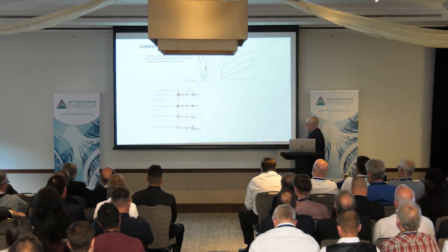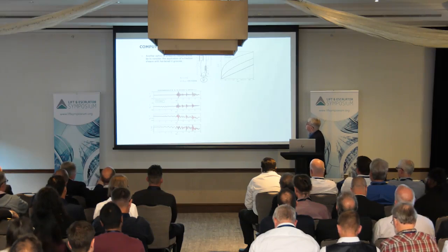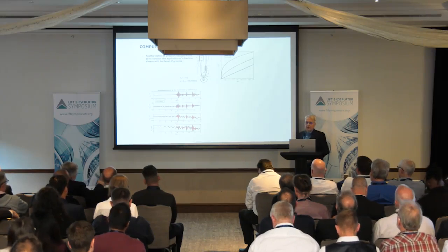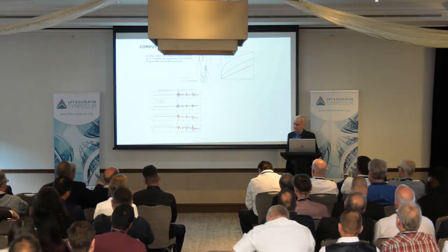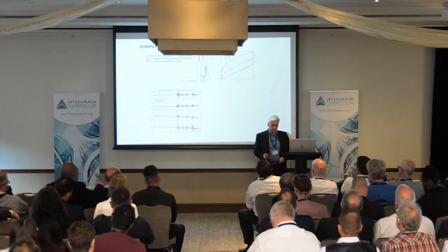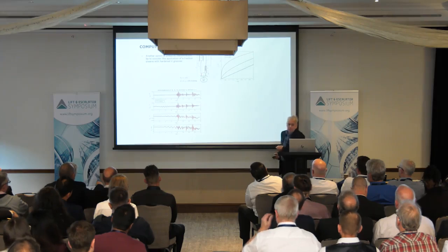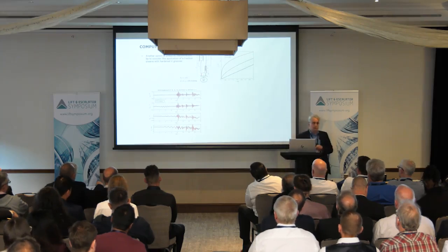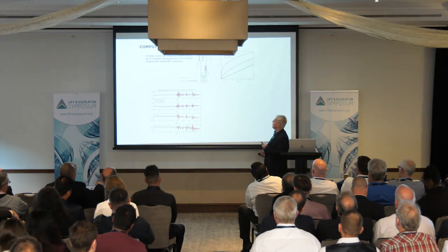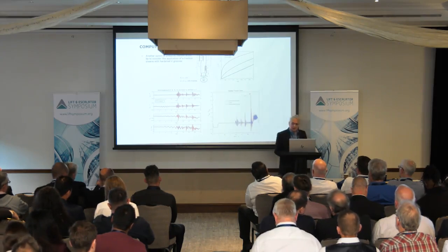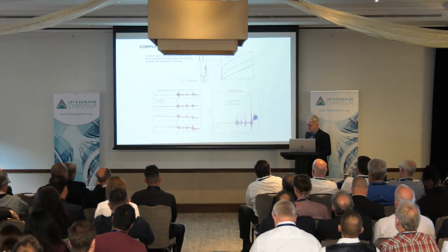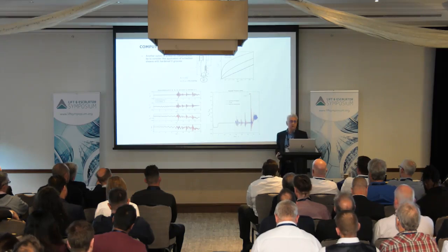So, if we take into account implementing another component into the system, which is commonly used in high-rise systems, it's called a tie-down. A hydraulic tie-down is attached at the bottom of the compensating sheave and to the pit, and this restricts motion of the compensating sheave assembly.